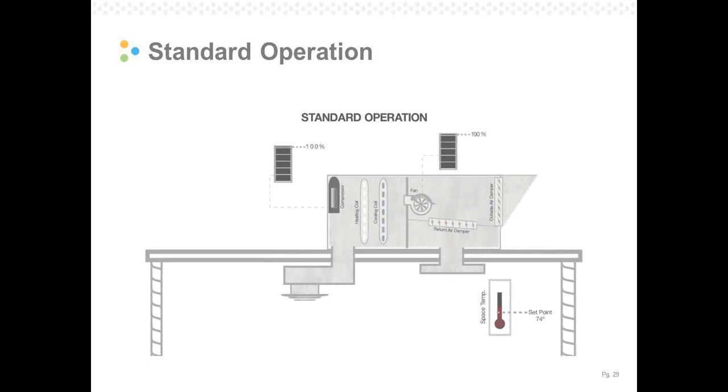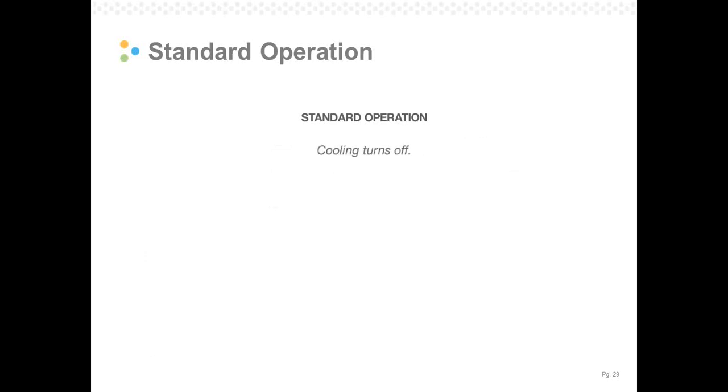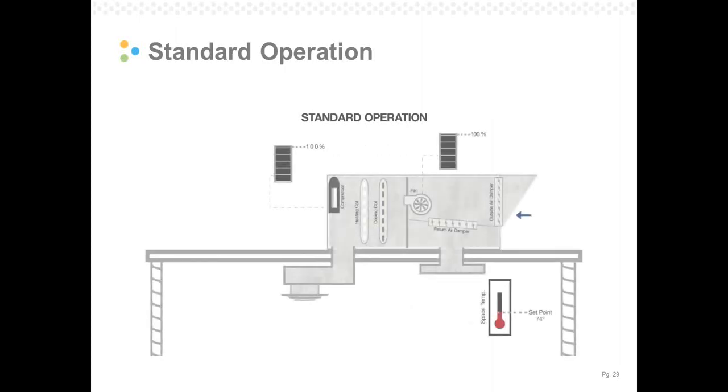As you can see from that narrative there, it's driving the indoor air temperature down. It gets down to a point where the set point is reached, and now the only thing that the rooftop unit can do, rather than cool off the space too far, is to turn off. That's depicted by the 0% compressor speed there. Note that the indoor air fan is still running at 100%. It's still pulling in outside air and return air at the same time, which can affect the discharge air temperature by going up and down in extreme weather conditions, whether it be hot, humid, or cold climate.